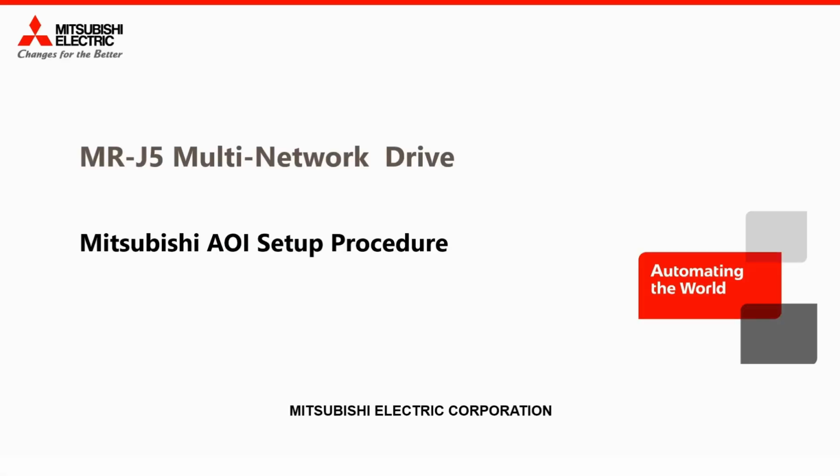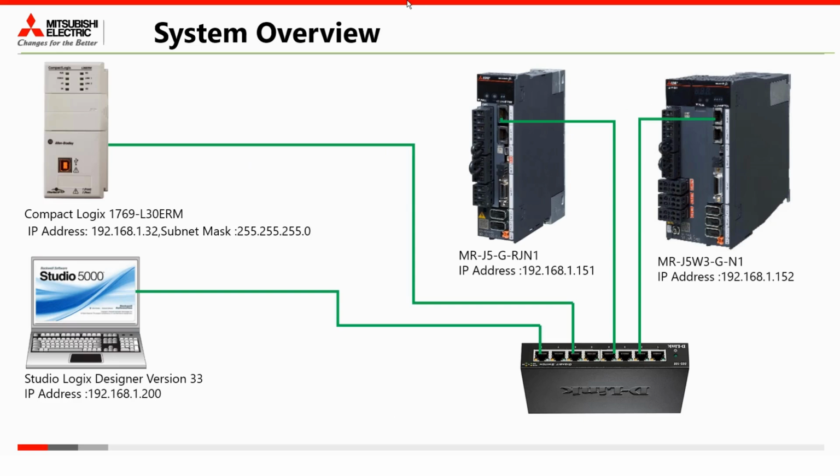In this video, I will demonstrate the setup procedure to run the MELSERVO-J5 Ethernet IP servo drive by using Mitsubishi AOIs on the Compact Logic platform. To create this video, I used Compact Logic's L30ERM PLC and two MELSERVO-J5 servo drives.